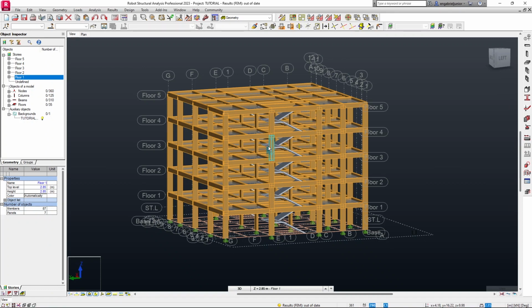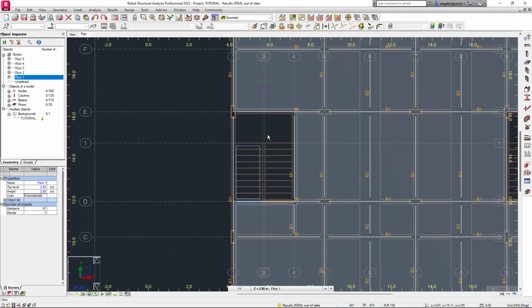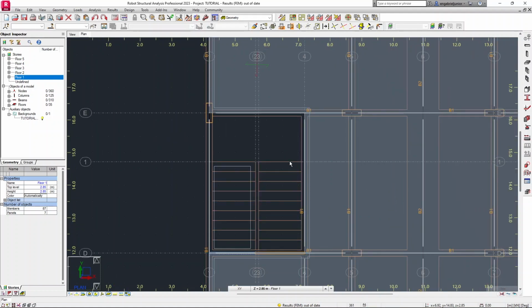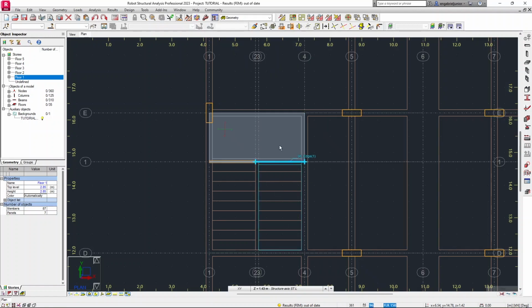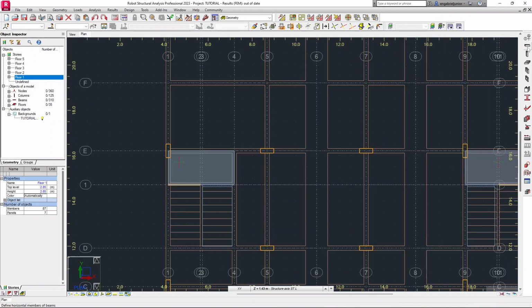Okay, so we're also going to add beams onto the landings here to make sure they can just be supported. So go to the plan. Actually forgot to do this. It's a large structure, so it might take some time. So we're going to move to the landing level. As you can see, I want a beam right here. So just select beams.